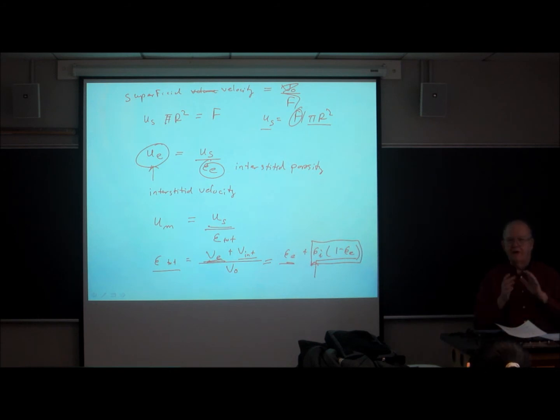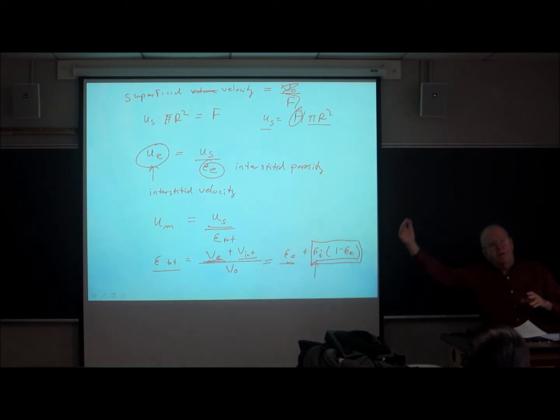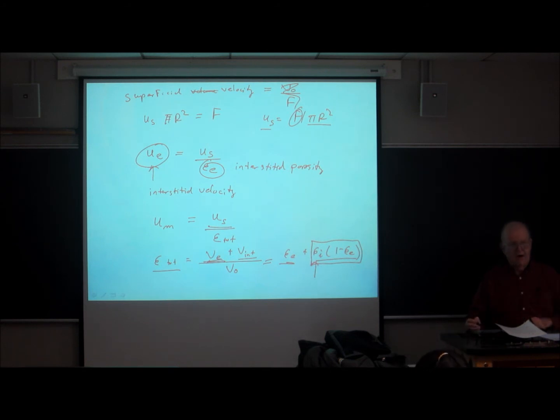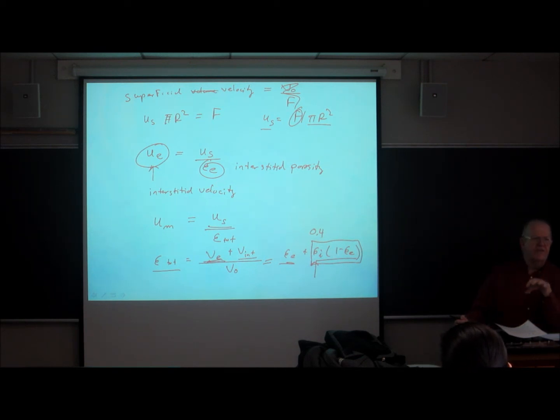There's a maximum that we can deal with in LC because of the high pressures, and because the pressures have gone up, the particles have had to be redeveloped so that they can handle the high pressure. But a typical value of an internal porosity of a fully porous HPLC particle will be about 0.4. So if we put in my estimate of epsilon E of about 0.4, we come up with a total porosity of the bed on the order of 0.6 or less.